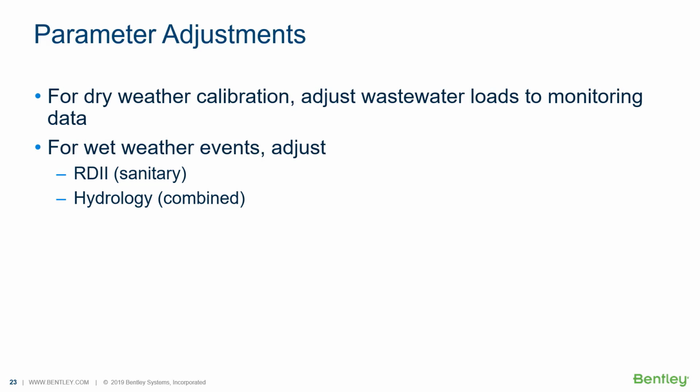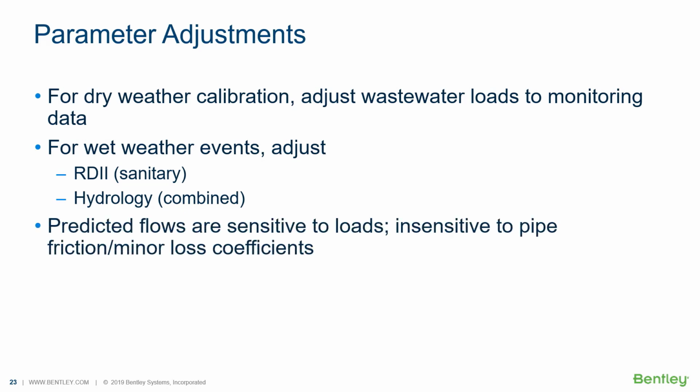Well, sanitary sewer rainfall-derived infiltration and inflow is really tough to track down. The surface flow into sewers, though, with stormwater or combined systems can be traced back with more logical methods that are more scientifically based, rather than the correlations which you have to use for sanitary sewer inflows.